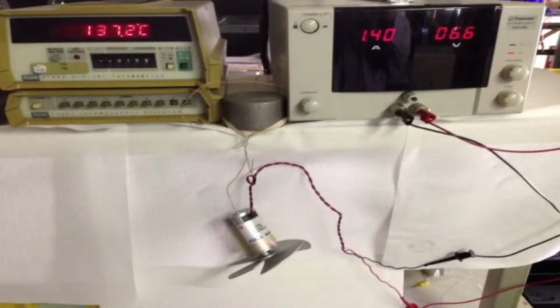Heat is generated inside the motor primarily by resistance to current in the windings. The test is stabilized when the maximum winding temperature, 150 degrees C, is reached. Additional heat is conducted through the connection contact between the motor shaft and coupling. In this case, a fan blade assembly has been set screwed to the shaft. You can see this reduced internal winding temperature by 12.8 degrees C.